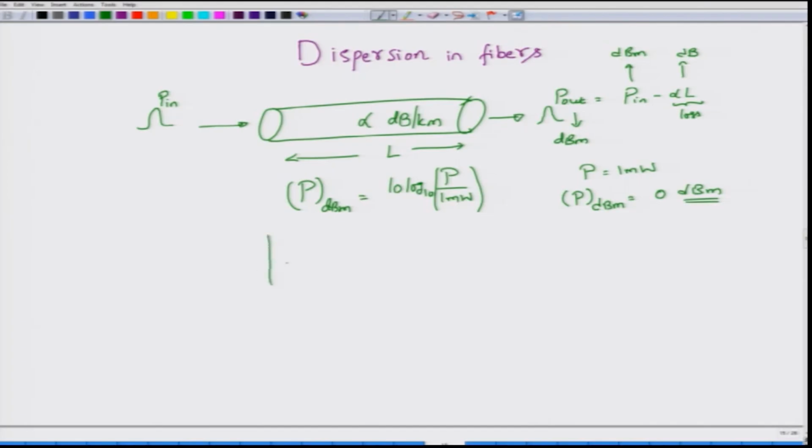For example, say we have a system in which I have an optical fiber of length L with an attenuation of 0.2 dB per kilometer, and let us say we go over 10 kilometers, just to keep the math simple. We then follow it with an optical amplifier. We will have more to say about this optical amplifier in other modules. Let us say it has a gain of about 10 dB. What would be the output power, provided the power launched into the fiber is 1 milliwatt?